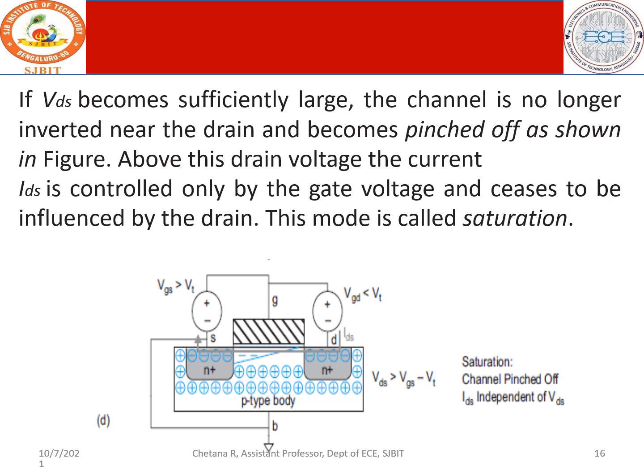When the region becomes pinched off, no electrons flow from source to drain. This is completely cut. So how much current is flowing? Whatever was the earlier current flowing, the same current flows here. It is saturated. So this is your saturation mode. This is how the three different stages of an NMOS device work. Basically we are in the first stage of accumulation mode, then it goes to inversion, then to the linear region, and finally it goes to saturation. So this is how an NMOS device works.